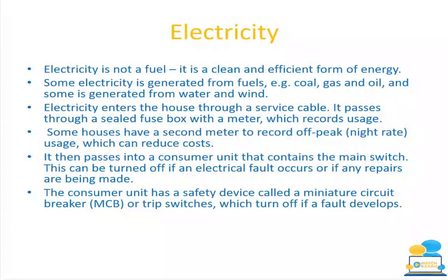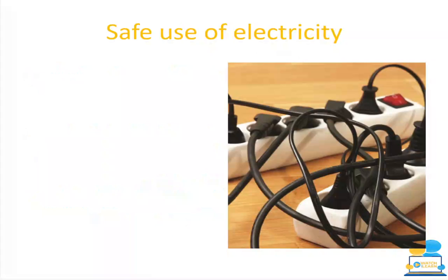For example, if someone is using the hair dryer and also has the hair straighteners on, and the oven is on, it might overload the system, and for safety reasons it will trip and you'll hear a bang. Then you go to your MCB, pull it back up and it'll fix the fault, and you know that you shouldn't have all the appliances going at the same time.